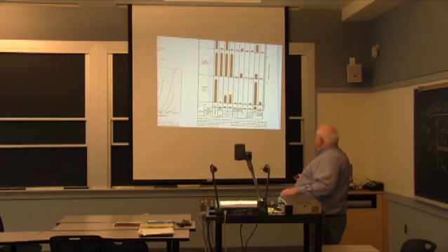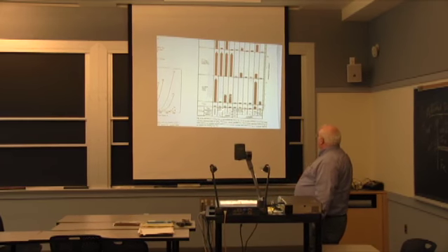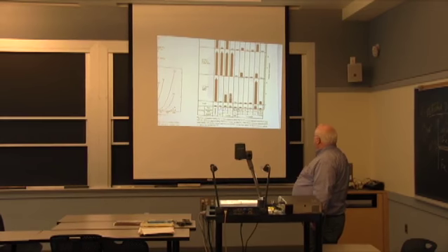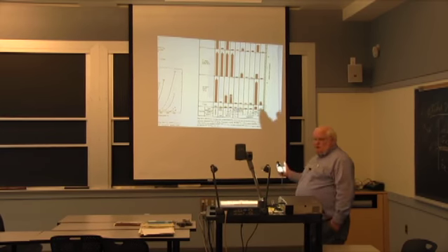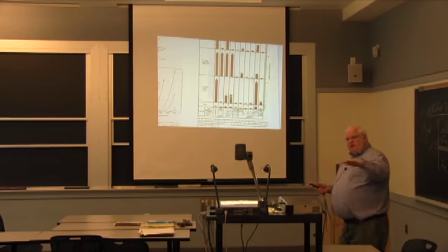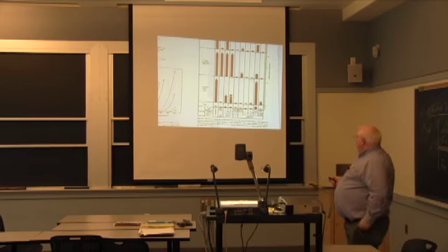And they're looking at different coatings. They could have had a resin lacquer, and we'll talk about what that is. Tin-plated copper, silver-plated copper, 60-40, this is the eutectic solder, so you pre-tinned it with the low-melting solder.